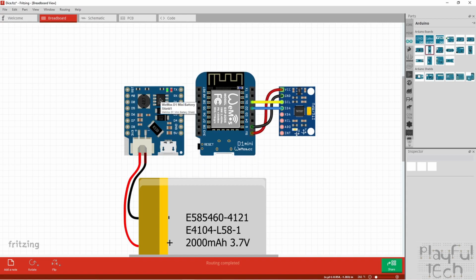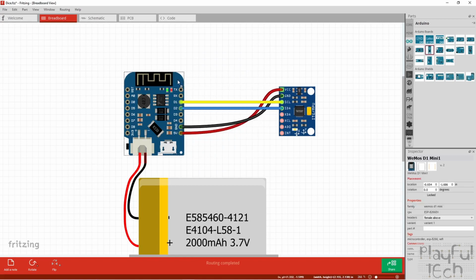This lets you plug in a 3.7 volt input from the battery, and it's got these components on board which will step up that supply to power the 5 volt line, and it will also regulate the power down to 3.3 volts, and it simply slots on top of your Wemos board like this, completely seamlessly, so it doesn't affect any of the pin output like that.